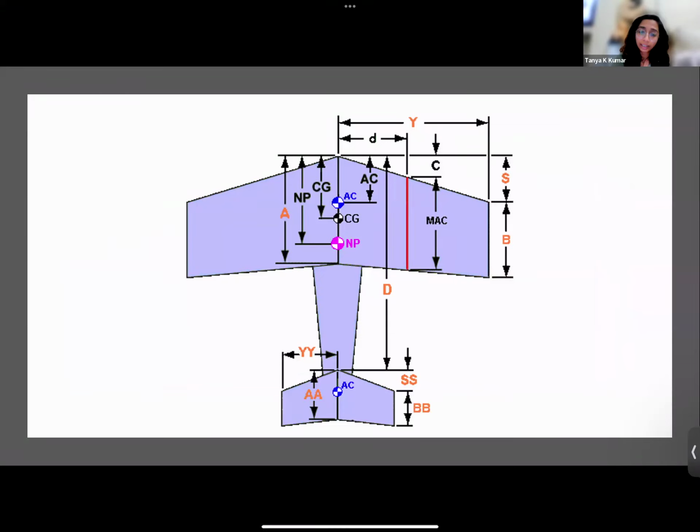Initially, the aerodynamic center was nothing but the AC. Now you can see that the neutral point is moved backward, towards the addition of the new aerodynamic surface. So if I add an aerodynamic surface ahead, it will move ahead. The neutral point moves along with the addition of new aerodynamic surfaces.